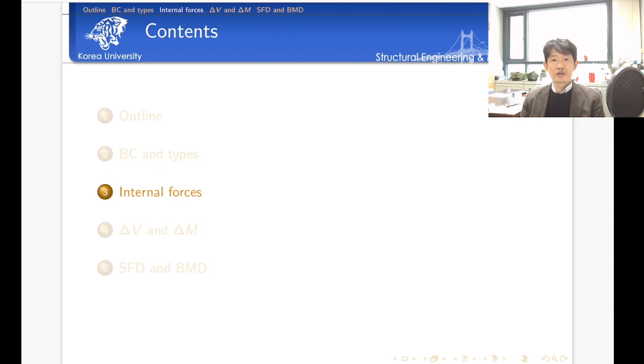If you integrate the stress or traction acting on the surface of a cross section, then we can obtain the internal forces. That's why I emphasize several times that the nature of internal forces is nothing but the correspondence of the stress field acting on the cross section of your free body diagram. In the case of torsionally loaded members, the internal force is called the torsional moment, which is the integration of the contribution of small shear stress over the cross section. If you integrate the contribution of small torsional moment over the cross section, we can obtain the torsional moment acting on the cross section.